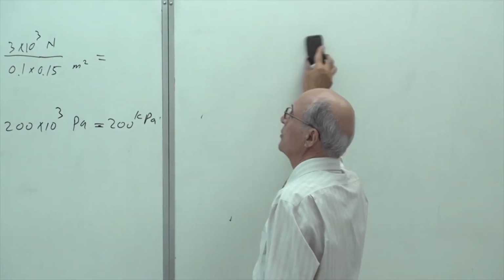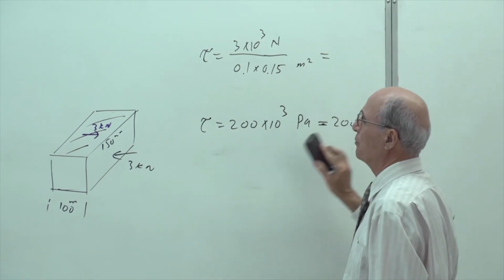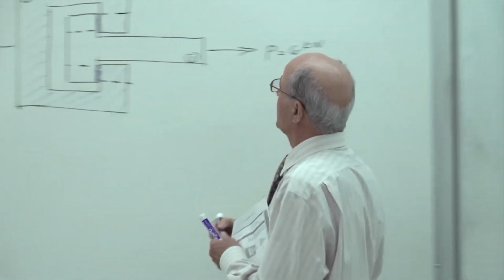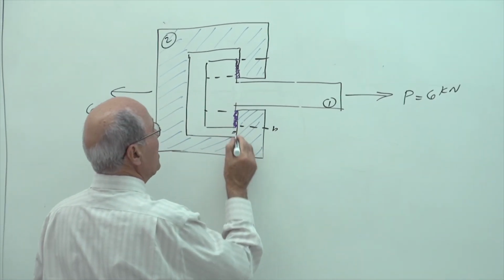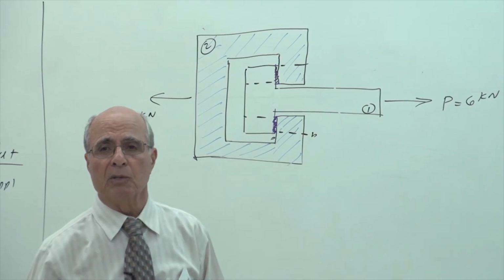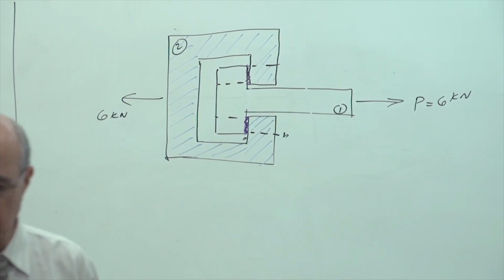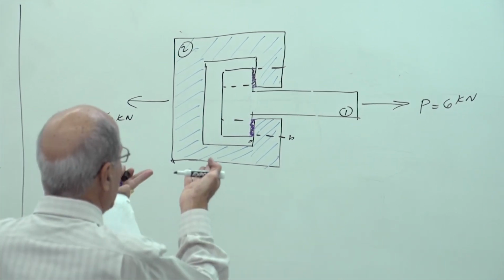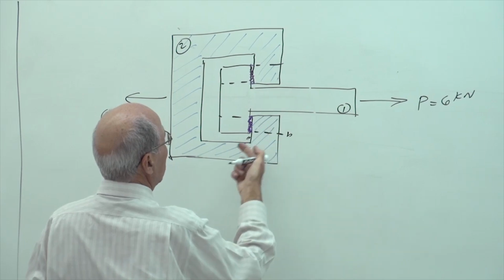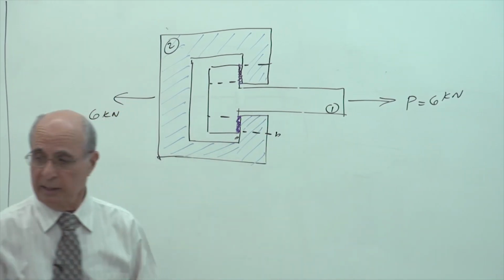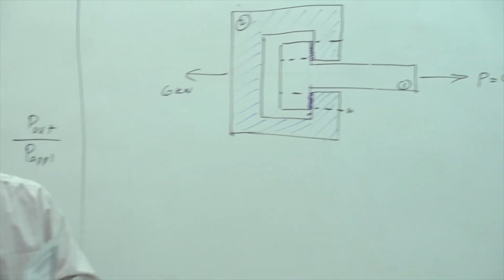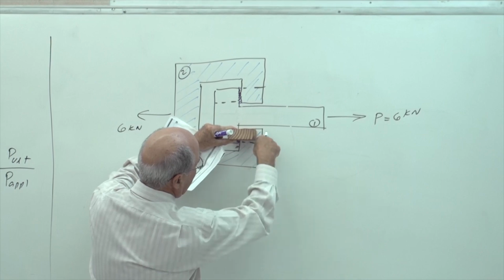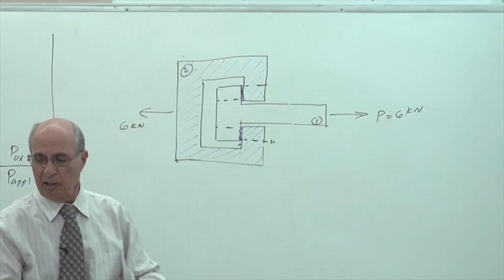Anyhow, what is the next tau that we want to calculate? That was tau in level AA. Now I want to calculate the tau in level BB, which is the cut in the blue material. What's the thickness of that one? The thickness is 1.25. Again, the depth is the same, so I have to look underneath it. This time it's a piece of material, this is solid. Here is 125, and here is 150. So that is the area being sheared off.